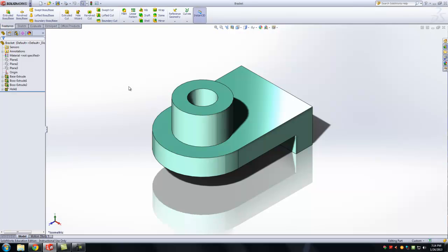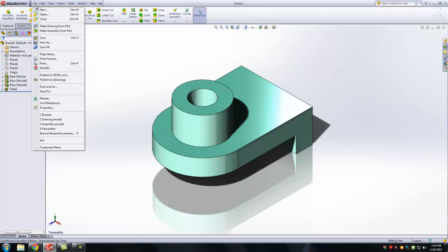apply it. So I'm going to give you about 5 minutes, or actually less than that. And I want you to go ahead and create a drawing. Go ahead and put the top, front, right, ISO, put the hidden lines, put the center lines and center mark, and basically get it ready so we can put dimensions on it.